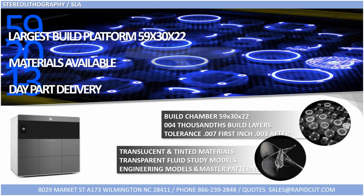Now, this process builds by curing a UV material, basically an epoxy form, at 4,000 layers in a stacked format. The tolerance for this process is going to be 7 thousandths for your first inch and 3 thousandths of an inch thereafter, and that's cumulative, starting at one side of the part and working towards the other. This process, however, is really